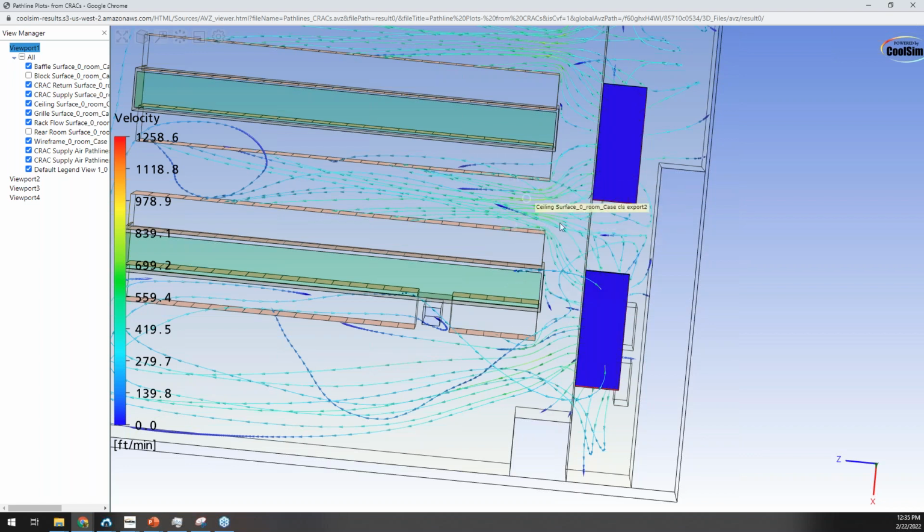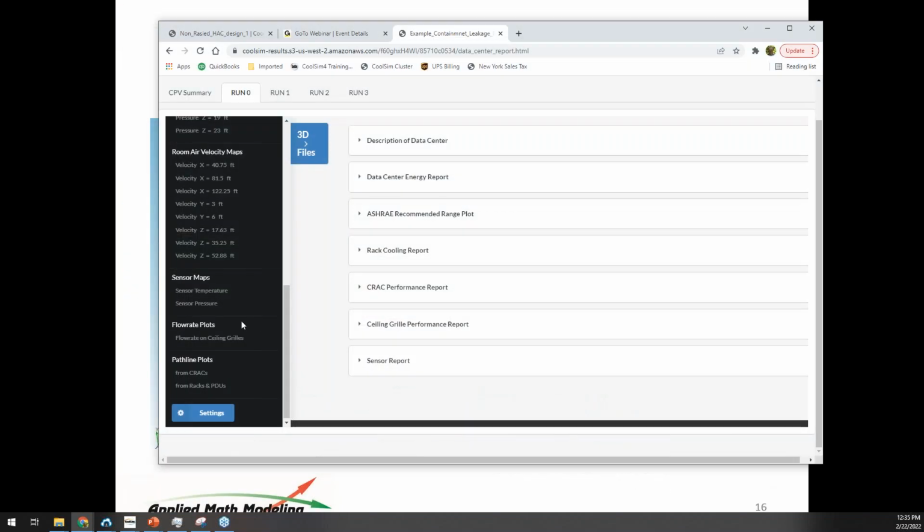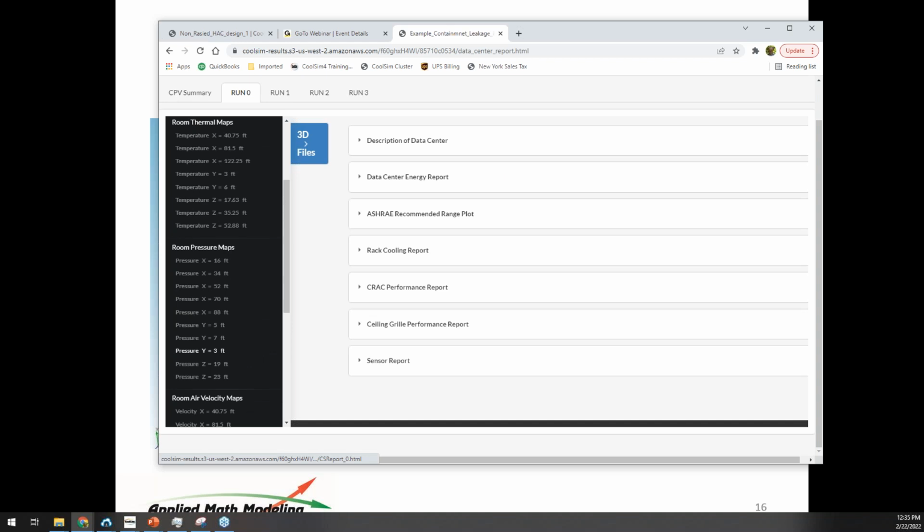Here we have a high velocity moving down the center. If I look at this on a velocity map, that will be high. Here I'm having a fairly high pressure, so there'll be low pressure there. High pressure here because the exhaust plumes are banging into each other, causing the static pressure to rise, and it'll begin to push back through those servers. So leakage in these servers is extremely important, and protecting them with proper blocking and so forth, the devil's in the details kind of thing.